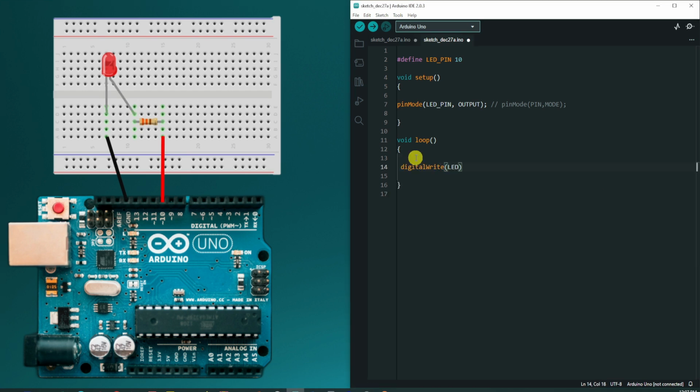With the LED pin, we need to turn on the LED, with giving some delay to keep holding that on. Whenever the LED is turned on, it should stay on for a particular time delay. That's why we have kept 1000 milliseconds, that is 1 second, and after the 1 second we will keep it as off.